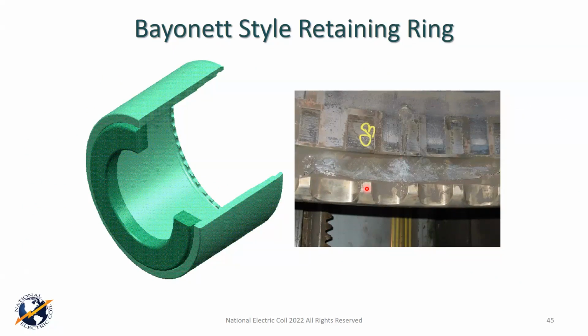They don't have a snap ring that holds it on axially, all right? But there's still a shrink fit in this trough, and obviously this one hasn't been cleaned up and prepared and NDE'd and ready to go back on, but hopefully you can understand what I'm saying there, and that's kind of what you're dealing with.